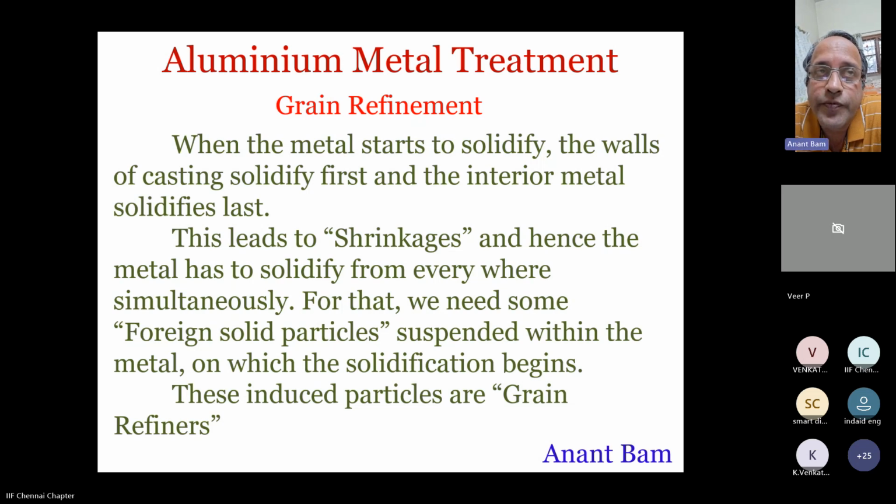So naturally, instead of 6 solidification phases, if there are 10,000 particles of titanium boron in it, solidification will begin at 10,000 locations. And if we are considering 1 liter or 1,000 cubic centimeter of aluminum volume, then 2% of it, that is 20 cc, will be the eventual shrinkage cavity.